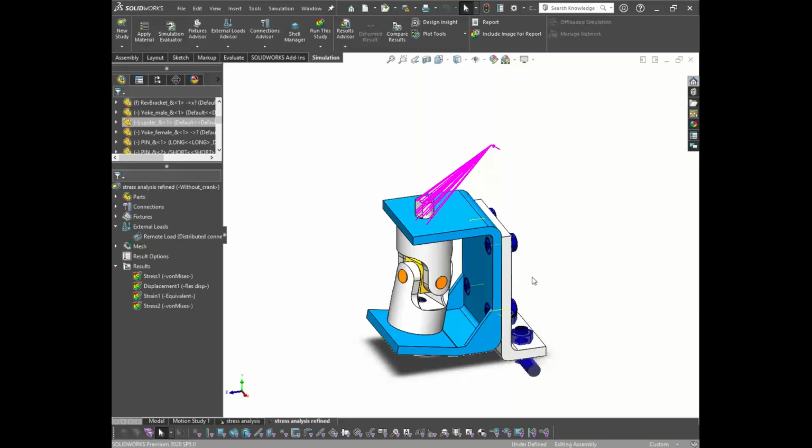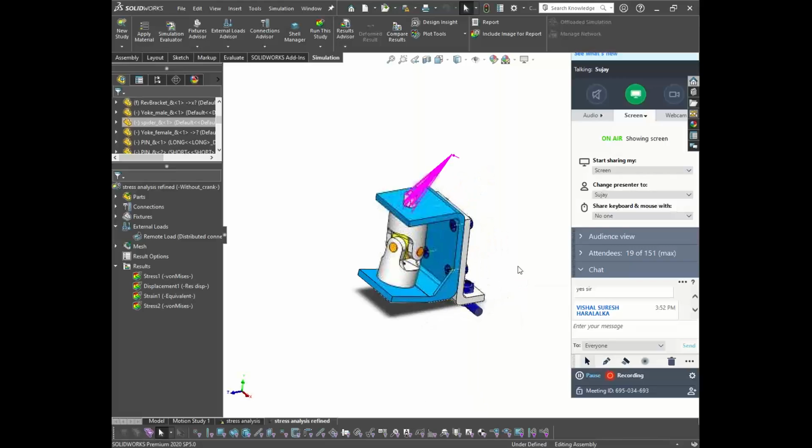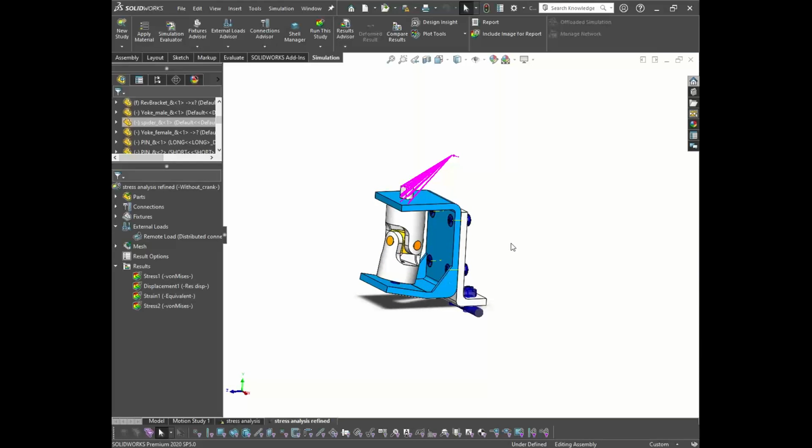So whenever we are dealing with assemblies, if the assemblies have different types of motions involved, we perform those motions in case of motion study. So suppose you are dealing with a piston cylinder assembly. The oscillatory motion of the piston due to the crank rotation can be captured in the motion analysis, but in order to import those boundary conditions, you cannot consider all the boundary conditions of an assembly. You need to import the different parts separately into the analysis.